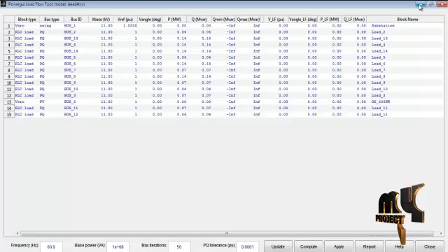We see which types of buses are used, whether swing, PQ or PV, and that is all mentioned in the bus ID and bus type. Then the buses have a certain base kVA, the reference voltage, and the angle of the buses, and also real and reactive powers are all given, along with the corresponding QLF.